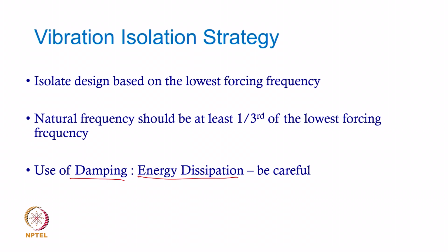Okay. So, do not excessively use damping, because it is going to be problematic for most of the frequency ranges. So, it is only good near resonance, and if you take care of resonance you really do not need damping at all. Okay.